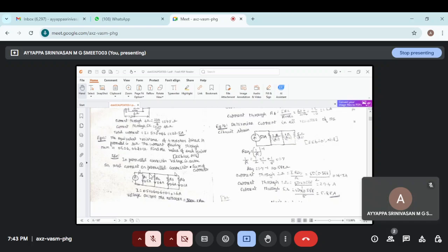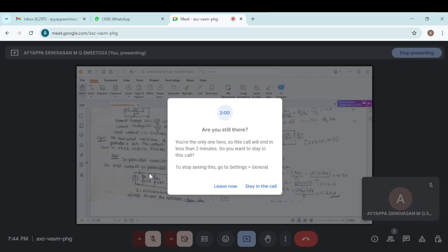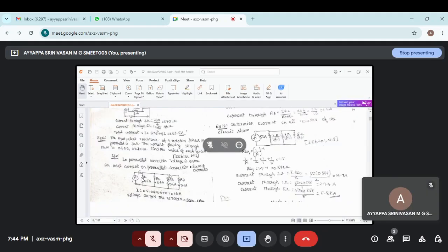So, let us consider total current now, right? The total current is nothing but, now consider how the resistors are connected. They have given us parallel. So, total current is the sum of all currents, 0.5 plus 0.4 plus 0.6 plus 0.1. So, the answer is 1.6 ampere. Now, we have found total current is 1.6 ampere and they have given total resistance is 30 ohm.